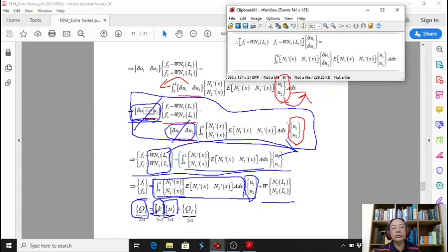So Q equals KU, and this term is a member force vector. So this is W times the vector N1 and N2. So this we call QF. So basically, the finite element method is the same as the stiffness method before. There is Q equal to KU, and then we need to add QF. So QF is a member force vector.